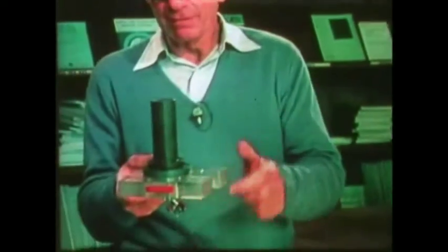We want to measure wave height offshore. An easy way to do this is to measure the pressure on the seabed due to the waves passing overhead. We do our recording on the island, run a cable offshore, and then connect it to a pressure transducer.